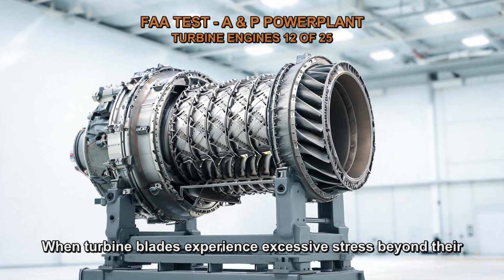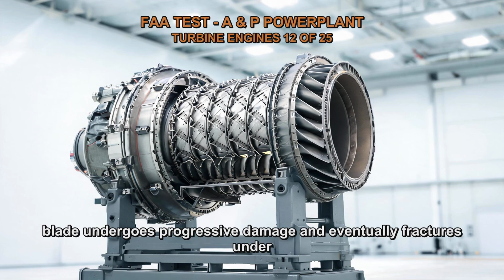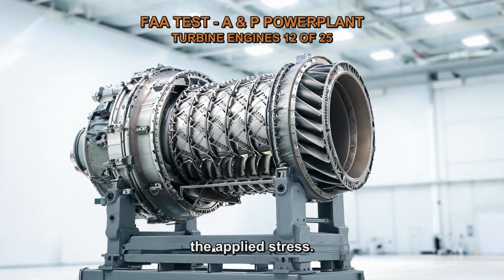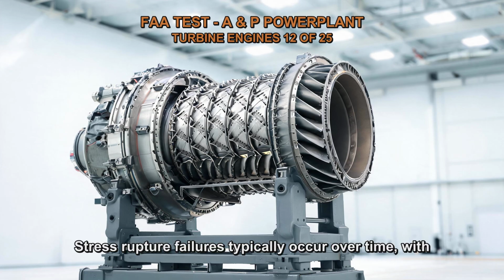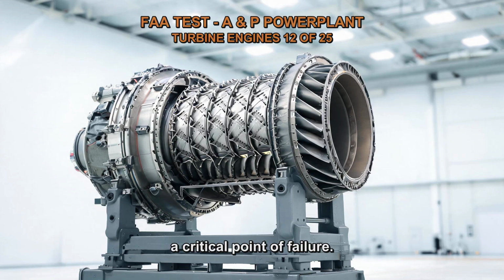When turbine blades experience excessive stress beyond their design limits, it can lead to stress rupture failure. This failure occurs when the material of the blade undergoes progressive damage and eventually fractures under the applied stress. Stress rupture failures typically occur over time, with the material deforming and weakening until it reaches a critical point of failure.